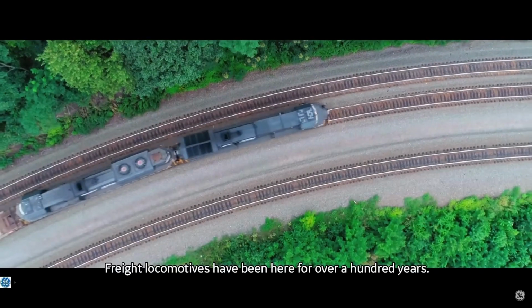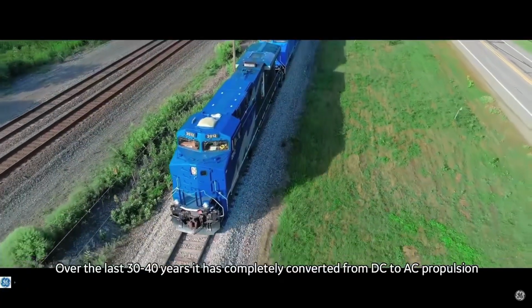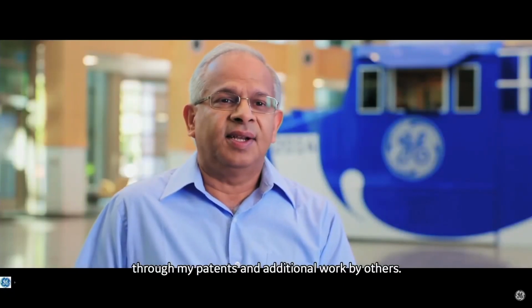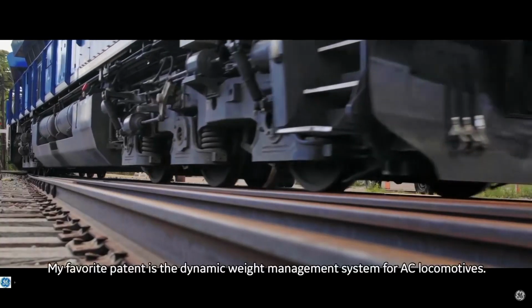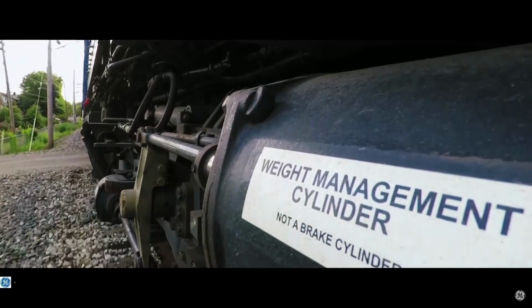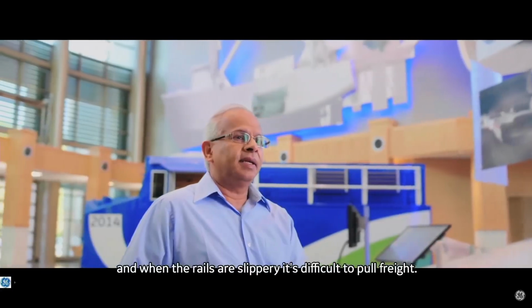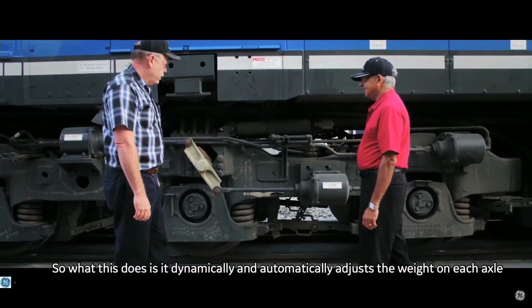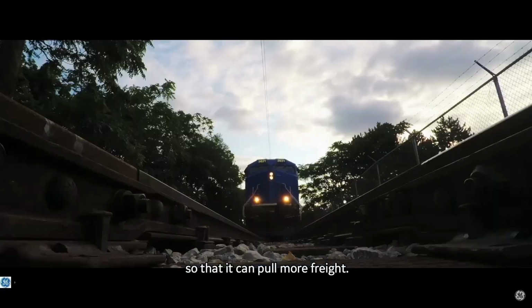Freight locomotives have been here for over 100 years. Over the last 30-40 years, it has completely converted from DC to AC propulsion through my patents and additional work by others. I want to say it's all me. My favorite patent is a dynamic weight management system for AC locomotives. Freight locomotives are used to pull heavy freight, and when the rails are slippery, it's difficult to pull freight. So what this does is it dynamically and automatically adjusts the weight on each axle so that it can pull more freight.